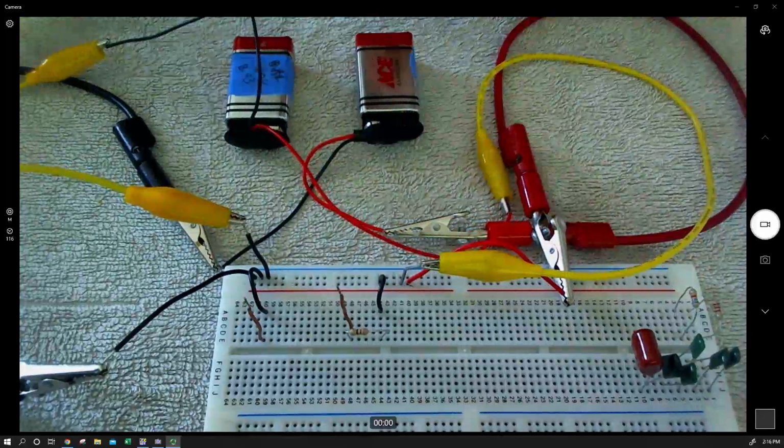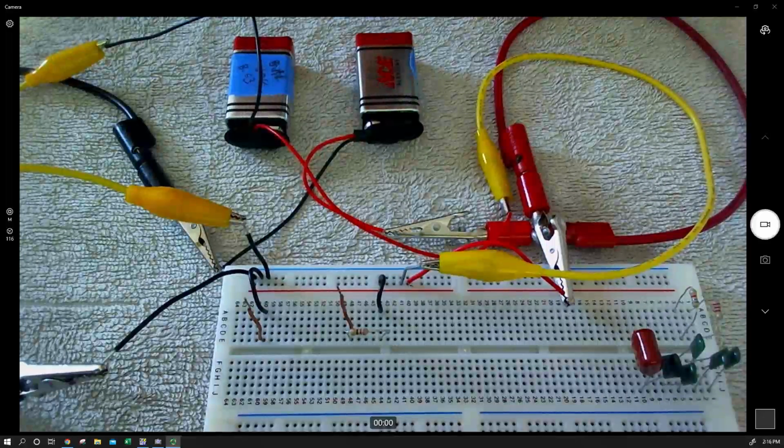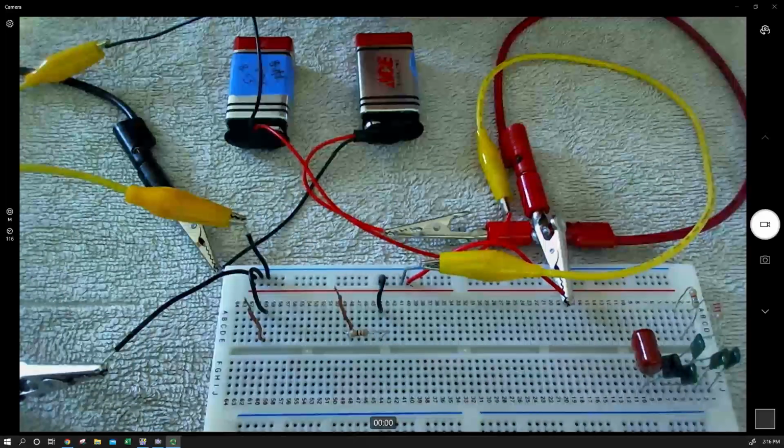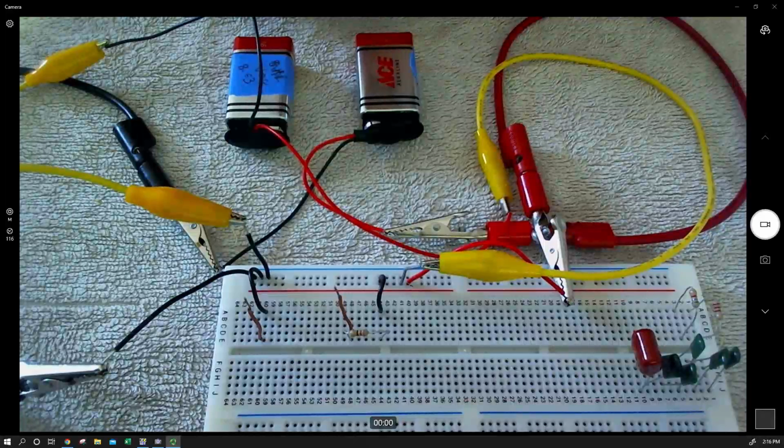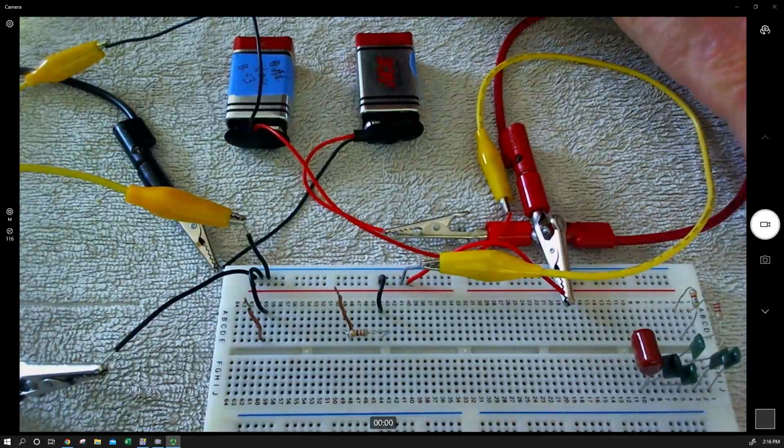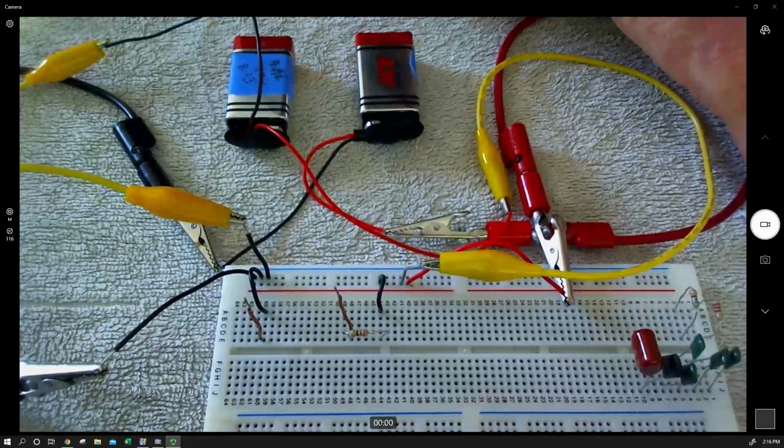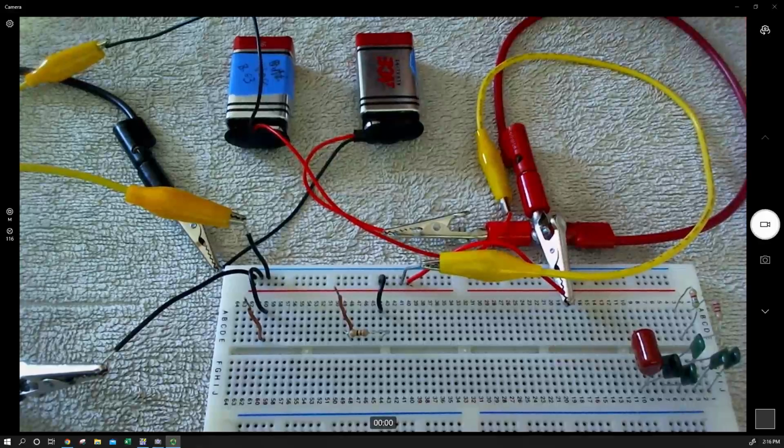Compared to a single source with the fairly low load resistance, we had a little bit higher measured current, and we held on to it a little bit better. And we'll note that down. So we'll say approximately 95. That's nominally the same. The big difference is it was a steadier current and not dropping.